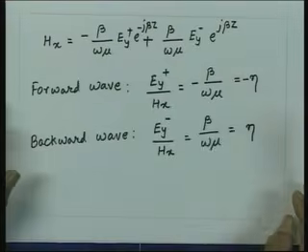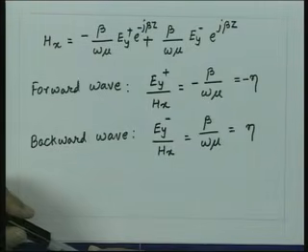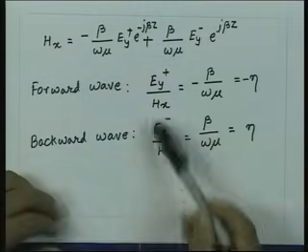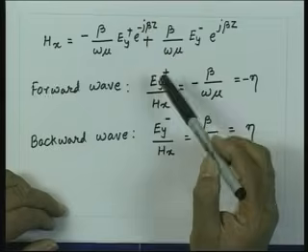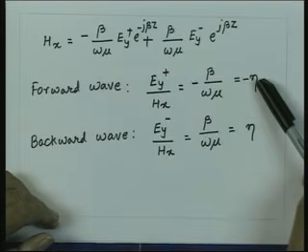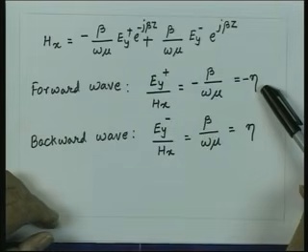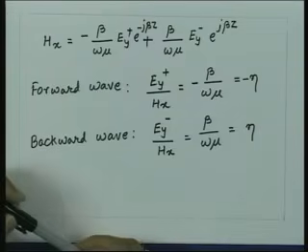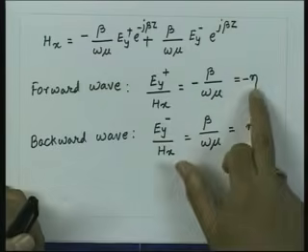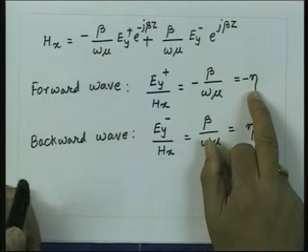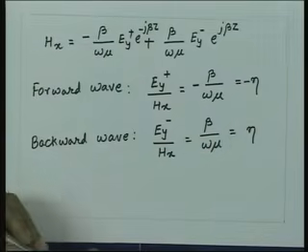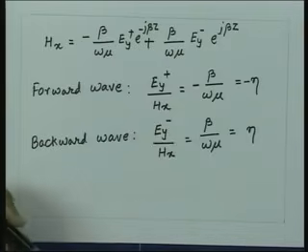So, earlier when the quantities were scalar for transmission line, the direction of these quantities was not coming into the picture. However, what we see now is that when we interchange x and y for E and H, the ratio of these two changes from positive to negative. What that essentially means is that the sign of this quantity not only depends upon the direction in which the wave is travelling, but also the orientation of the electric and magnetic fields.